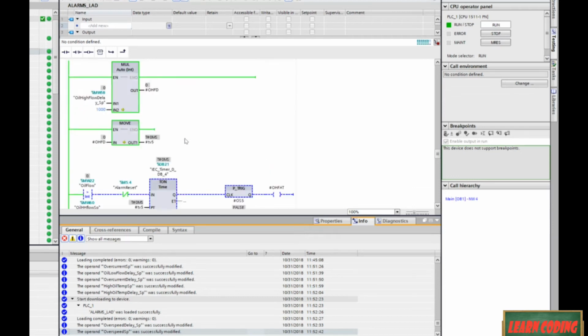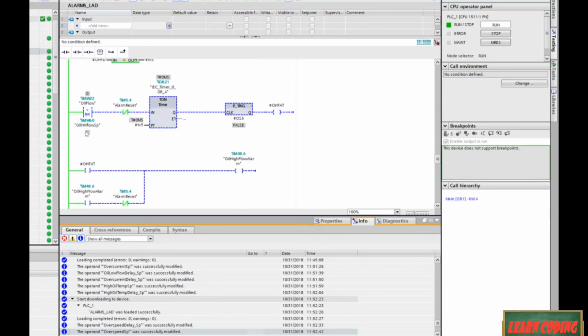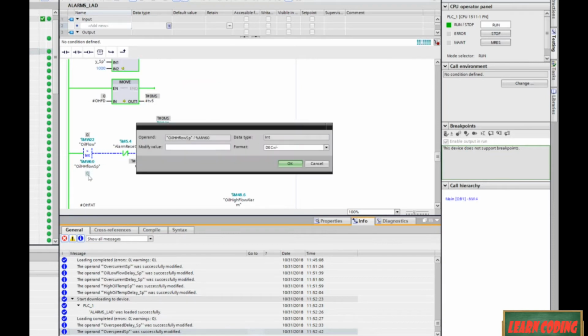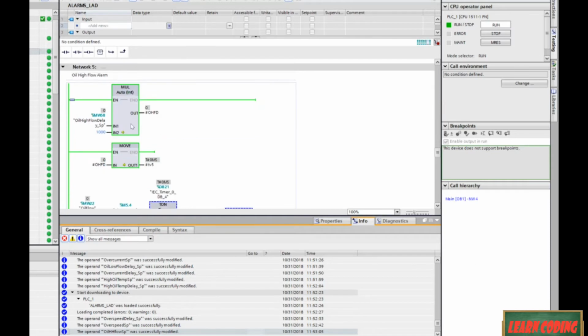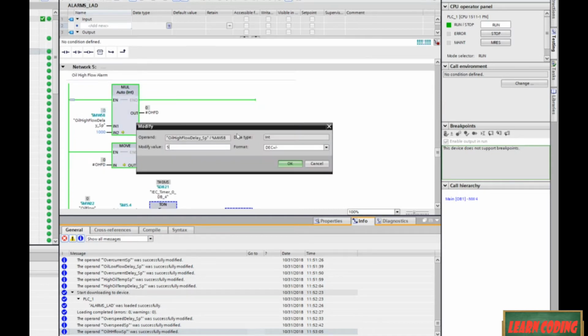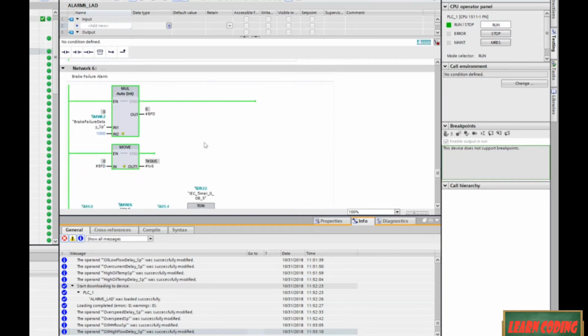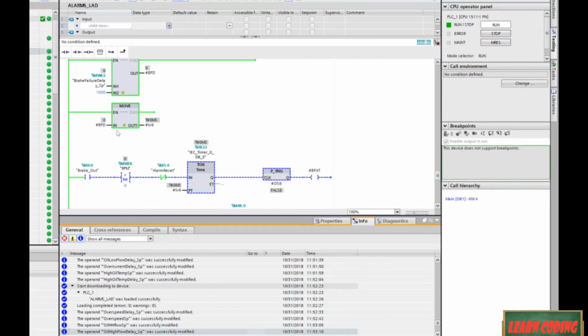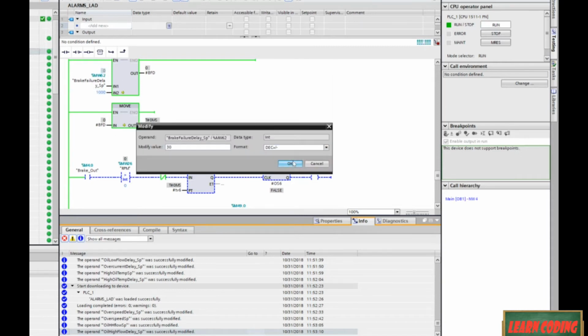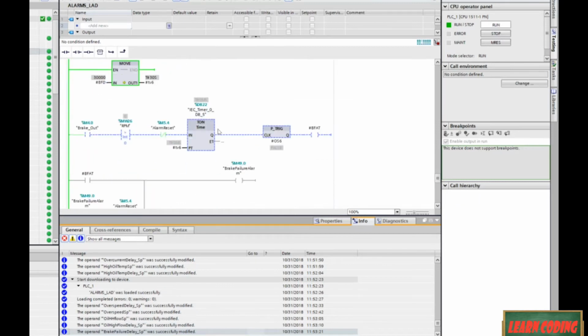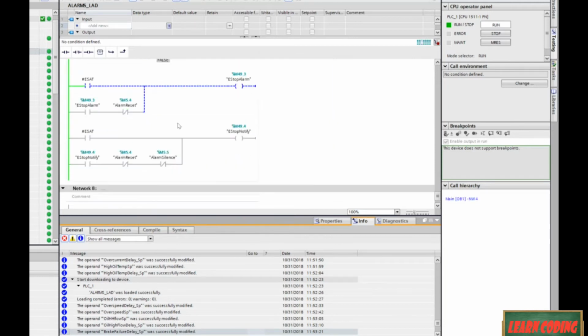We've got high oil flow, so we'll put that up to something like 40 gallons for 5 seconds, because I want to make sure that we just don't get any alarms. And our brake failure, that's probably our most important set point for time. So let's go ahead and say it's got 30 seconds to come to a complete stop. Okay, and yeah, I think we've got it from there.